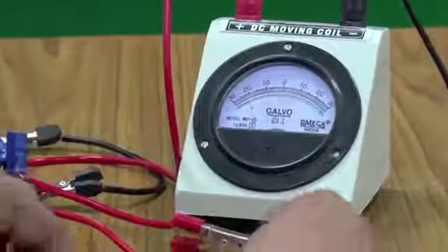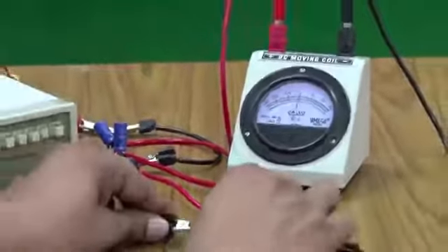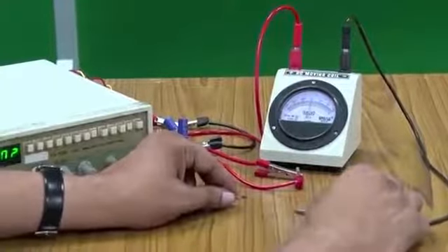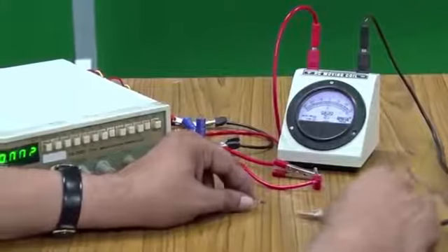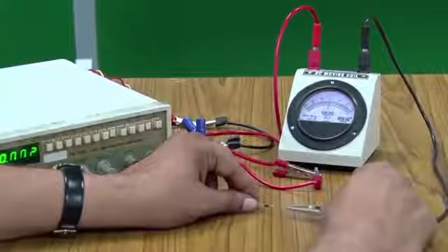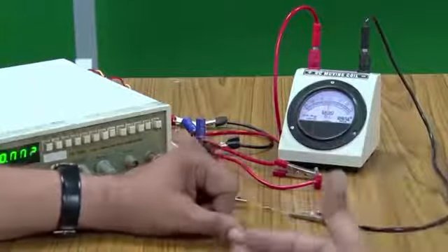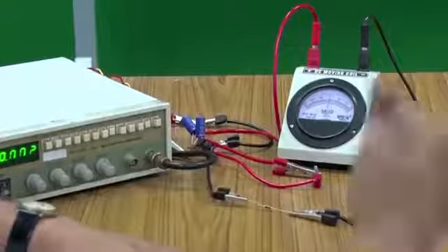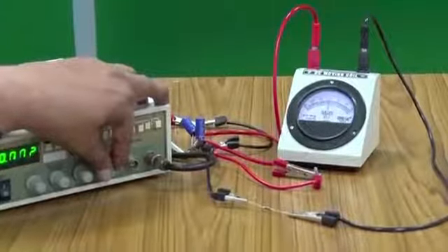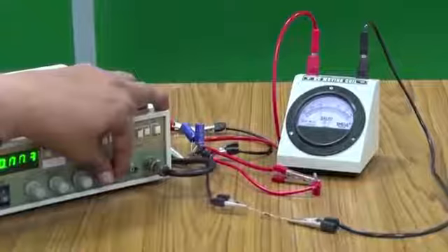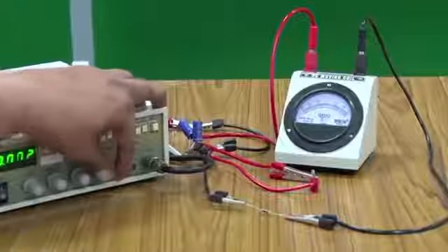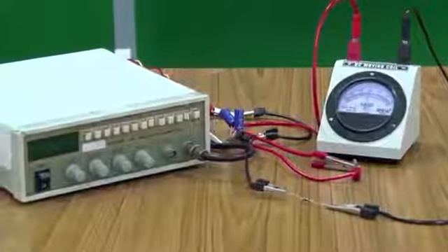So, that shows that this assumption that we had taken, that just forward bias and you have large current, that is not true. You have to supply some initial voltage, after which that characteristic, IV characteristic, the exponential part starts, only then it works. So, let me increase this voltage and you can see that yes, now it has started going. All right. So, we will stop today's lecture here.